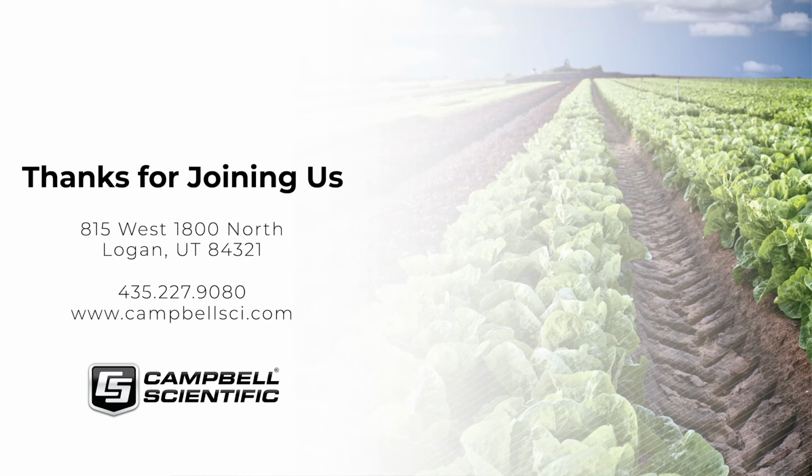Yeah, let me just throw this in there. The effect will be more noticeable near the surface, where you have greater temperature fluctuations throughout the day, and you might see something along the range of plus or minus 0.02 that's caused just by temperature. So it looks like your water content is changing throughout the day and the night, but it's really not. It's just the effect of the permittivity of water. And it's a bigger effect the wetter it is.